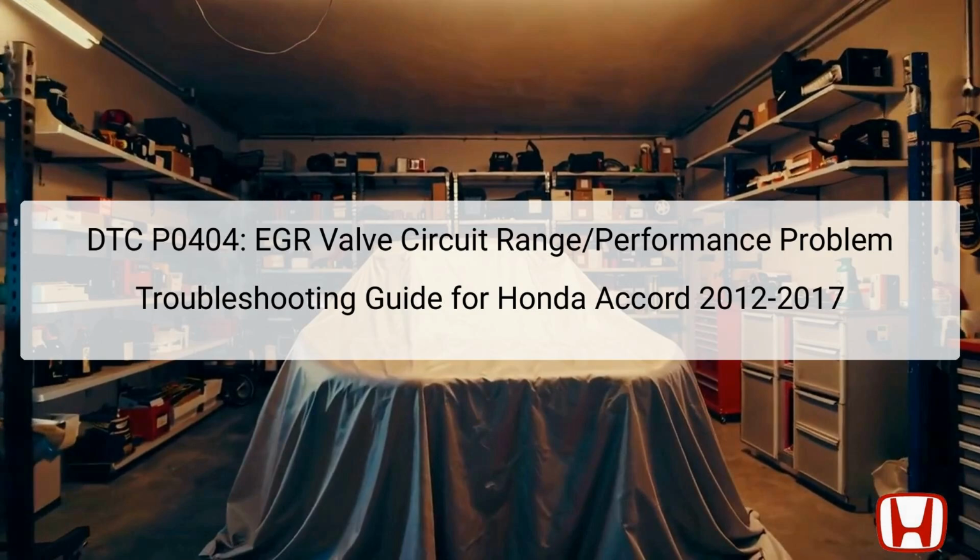This presentation provides a comprehensive troubleshooting guide for the DTC P0404, which indicates an issue with the EGR valve circuit range or performance in Honda Accord models from 2012 to 2017. The focus is on diagnosing and repairing problems related to the exhaust gas recirculation (EGR) system, specifically the EGR valve and its associated circuits. Understanding how the EGR system works is essential, as it recirculates a portion of the exhaust gases back into the intake to reduce emissions and regulate engine performance.